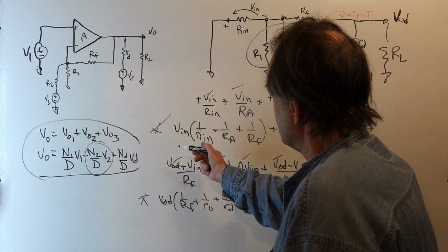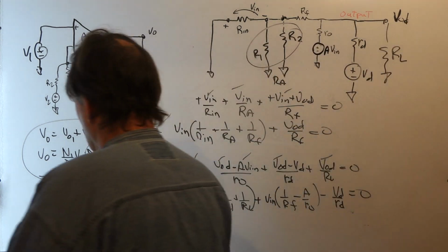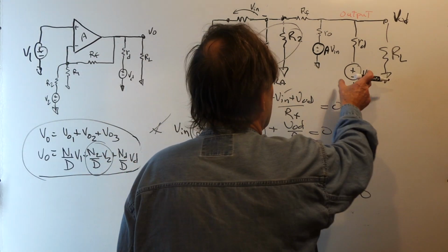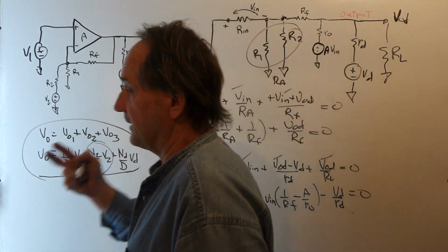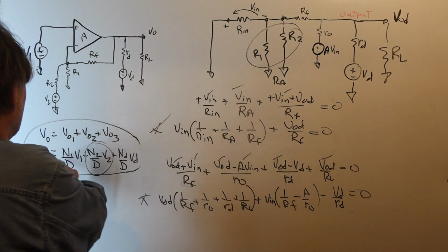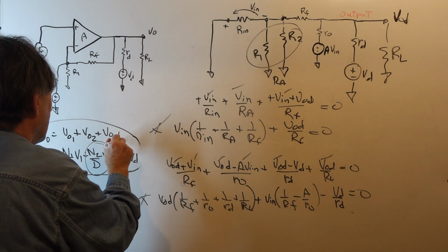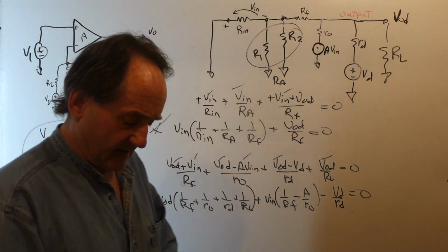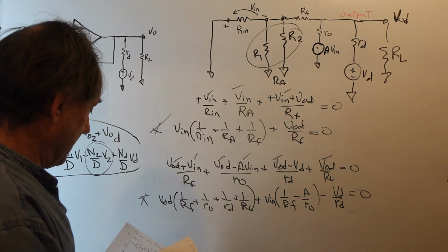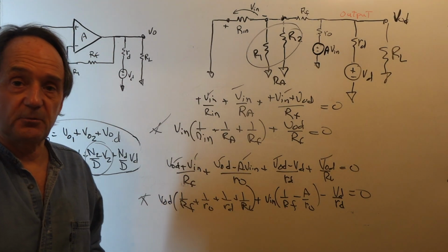So, if you solve for Vn in this equation, put it in this equation, and crank it out, you'll get the contribution of VD to the output. Then you add the three outputs, VO1, VO2, VOD, like this, and that'll get you the same answer as I got when I solved the network at the beginning of the video. So that's how you use superposition.